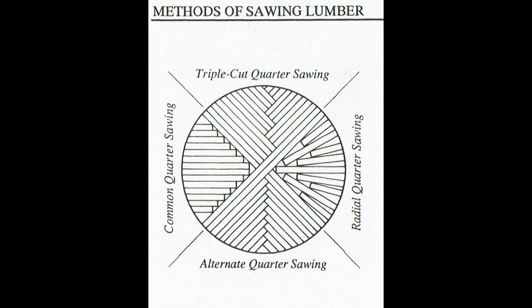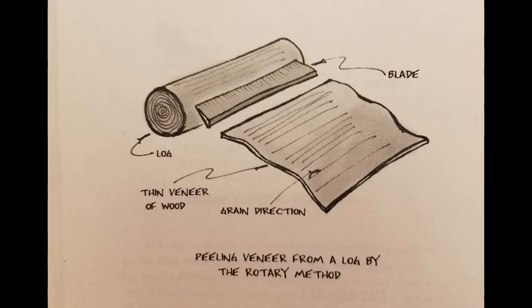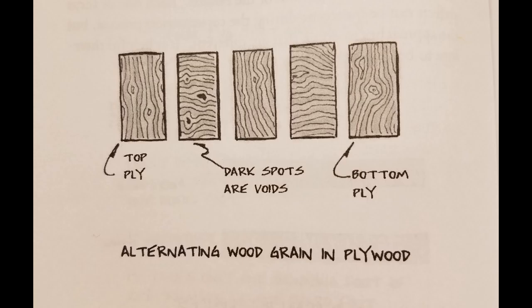And then here you can see how plywood is made, and it's basically how a log is rolled or spun close to a stationary blade, and that blade will cut away whatever thickness is desired or chosen, and it'll create that veneer sheet. And as those veneer sheets are cut, processed, and dried out, they are then alternated to create the various layers of plywood.